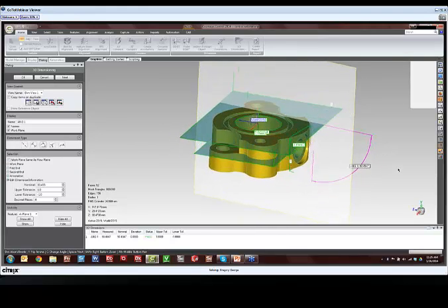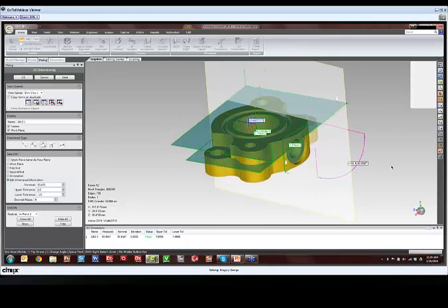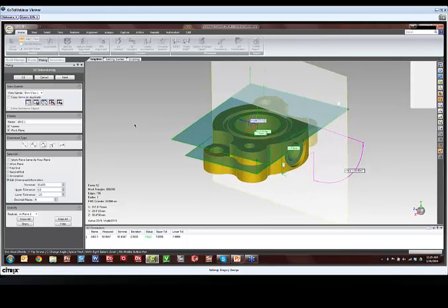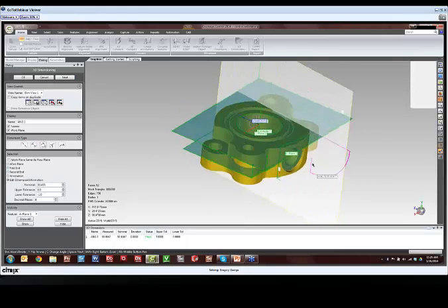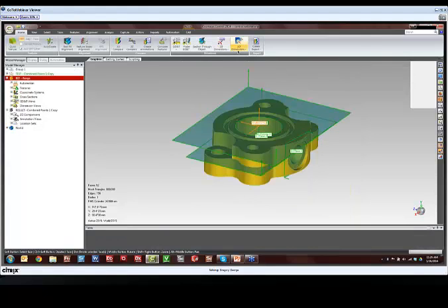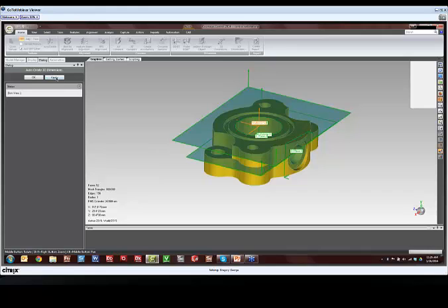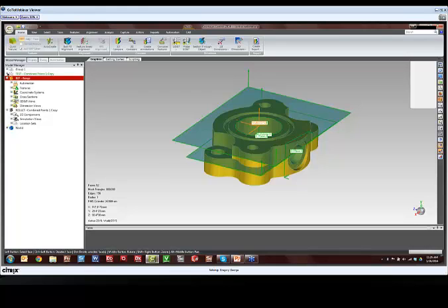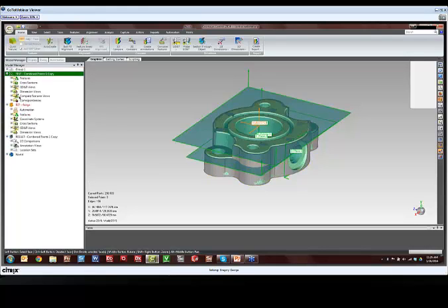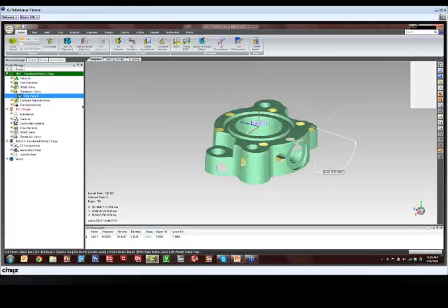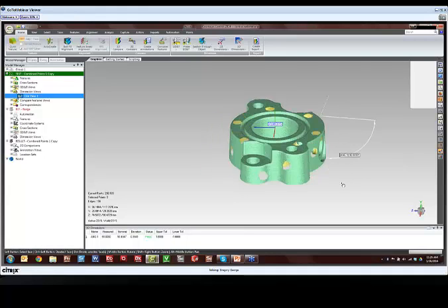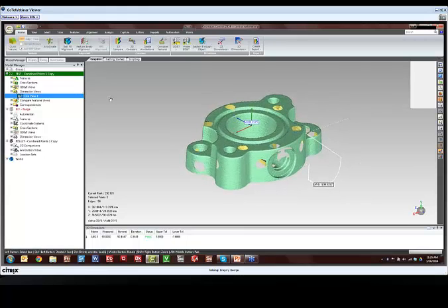Select that plane, and pull out a measurement. Now right now we're making a measurement between the two planes on the CAD model. So what I'm doing here is I'm going to go ahead and make that plane measurement on the CAD model first, and then we'll automatically create that same measurement over on the test data. So if I hit apply, you'll see here that it says OK, and I can come over to the test data and turn on my dimension view, and you see here that it measured that as 90.8090 between those two planes.